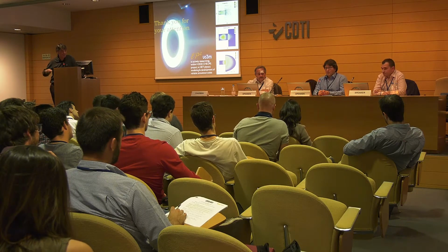For them, what is important is that the business case is good. So if they make money, they don't care. And making money is sometimes not only about the capabilities of the thruster, but the whole business plan. For example, for how long are you going to be thrusting without getting money, all this kind of stuff. So you see there is a place for every technology at this moment. And there is even another technology, the HEMP, which is something between the ion and the Hall. It's maybe not as good as the ion, not as good as the Hall, but it has the capability of having very cheap electronics. So there are always new things coming, and you cannot say this is the best or not. What is true is that the Hall effect thruster today is the most widespread and the one that is most sold in the market.